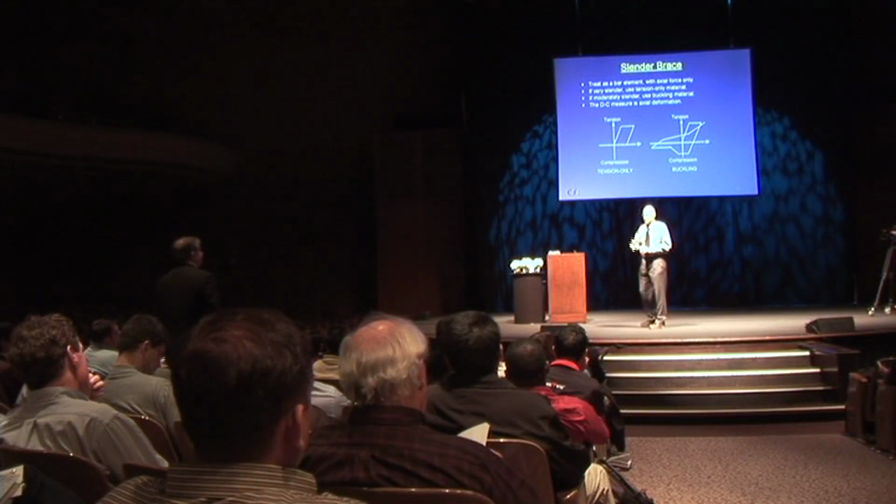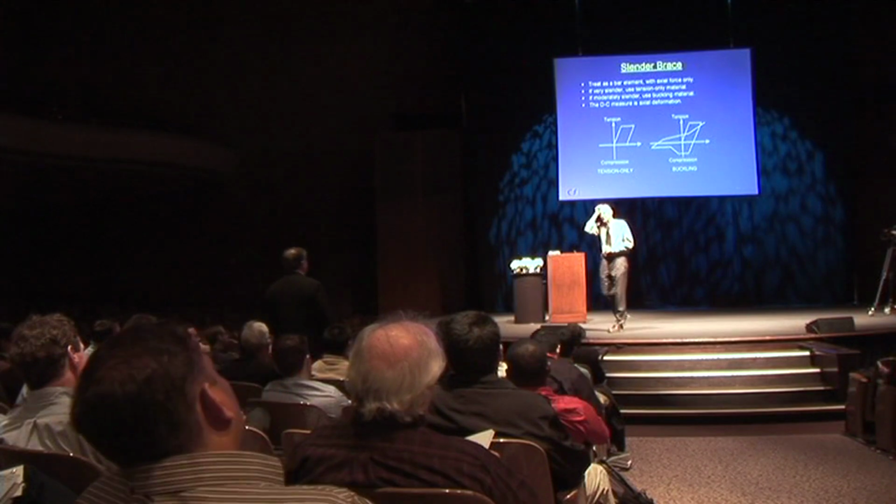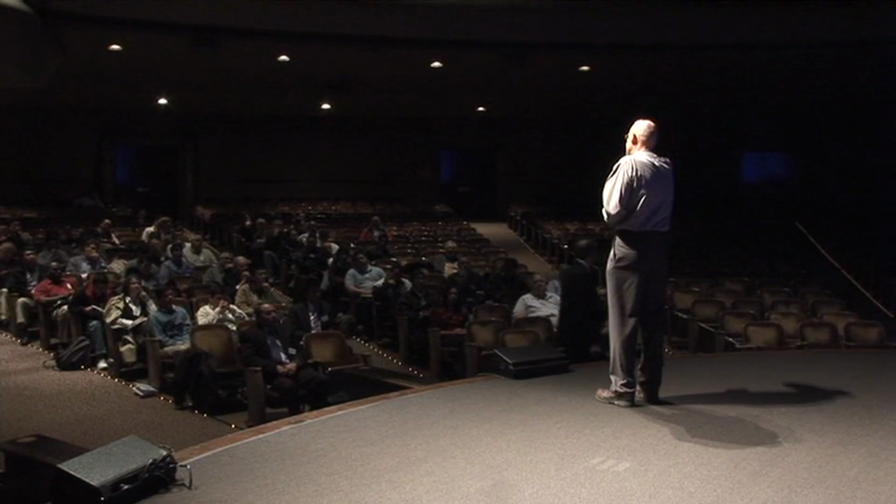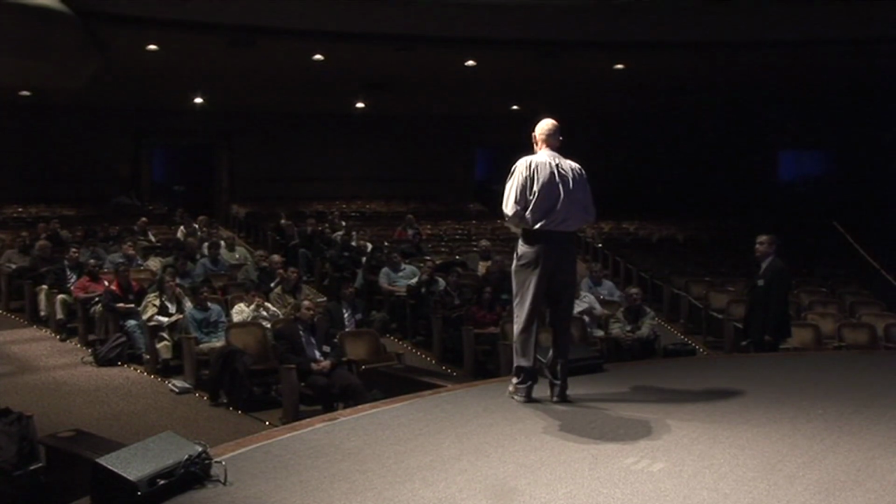Well, I will talk actually about floor diaphragms a little bit and shear walls. If it's not okay to assume a rigid diaphragm and you have to model it as deformable, then you've got to model it using elements. And that's not an easy thing to do, and it does also increase the computer time rather dramatically, unfortunately. It can be done. Perform has quite a number of elements that you could use to model deformable diaphragms. I'll say a little bit about it when we're talking about shear walls.